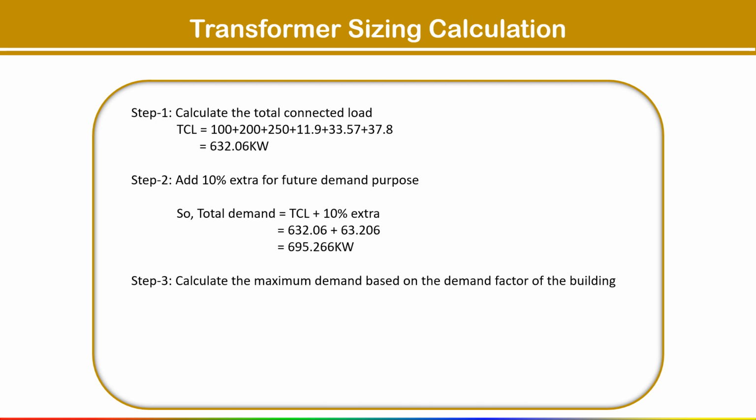Here the standard demand factor is given for residential building and commercial building, because based on demand factor only we have to calculate the maximum demand value.